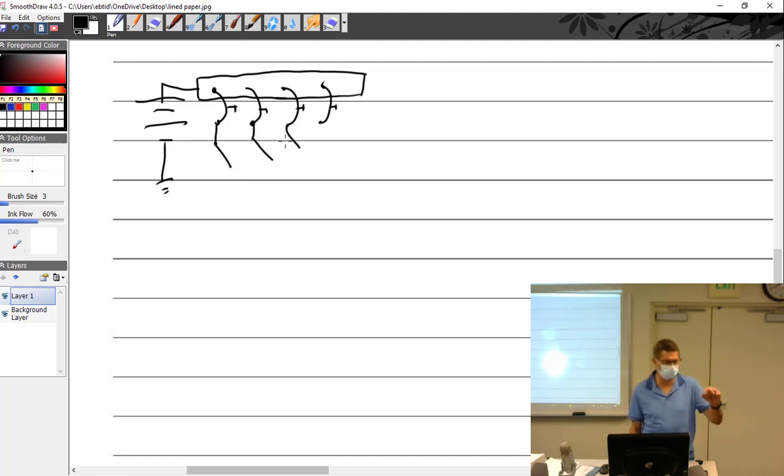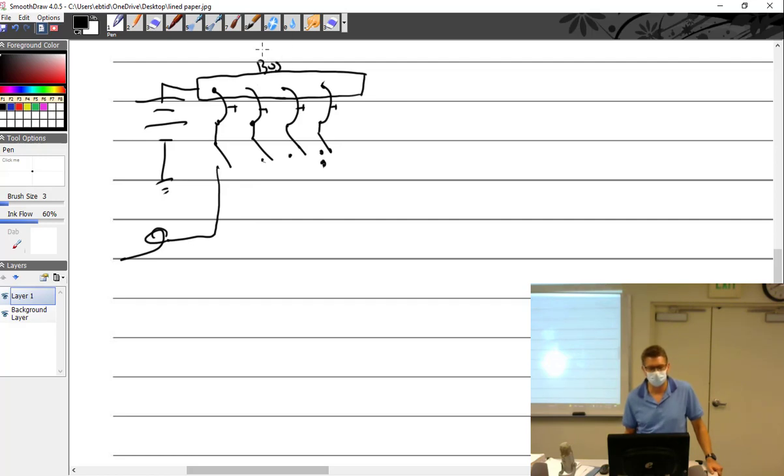And the switch is usually just, I don't know, an inch or so away. So that wire is only about an inch, and it goes to the switch. And then from there, you would control your components. Then it'll go out to the wing, and give yourself a landing light or whatever you have. So you have the bus bar, and then your circuit breakers. And that's how it really looks in an airplane.